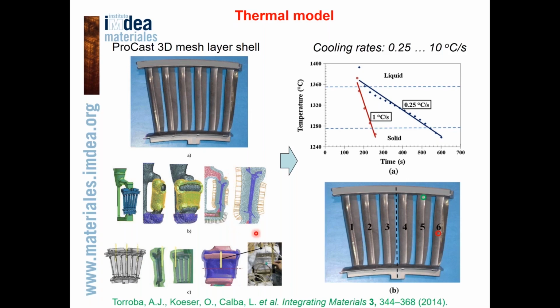The theoretical results were experimentally validated via real investment casting of a nozzle guide vane, where thermocouples were fixed to different spots of the complex shape part, and temperature time plots were recorded during the investment casting process.